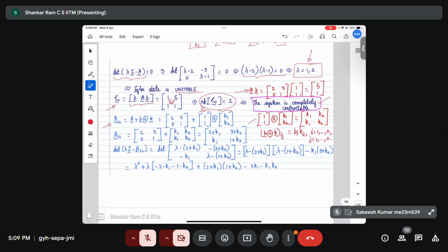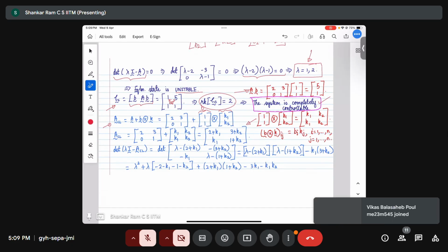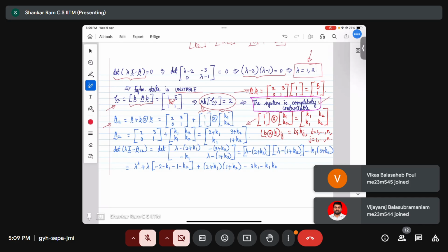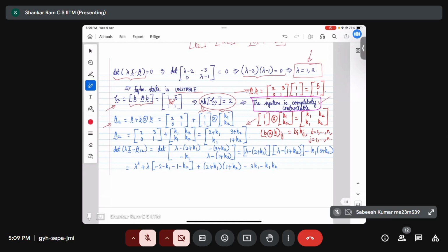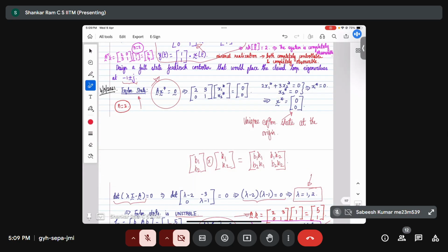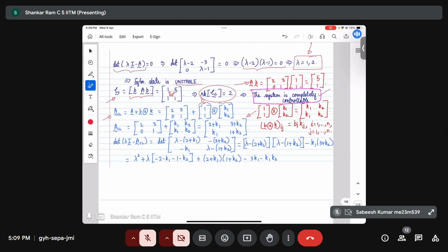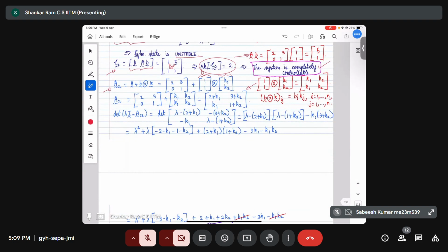And if we calculate the closed loop state matrix, you will get this as the closed loop state matrix. Okay, so I think you will have this as the closed loop state matrix. And what is our design problem? We need to place the closed loop eigenvalues at -1 plus or minus j. So we essentially want to calculate the closed loop eigenvalues, right? Or the eigenvalues of the closed loop state matrix.